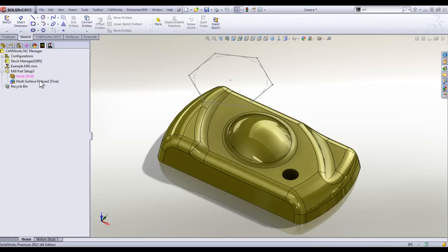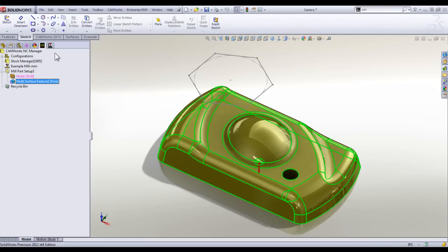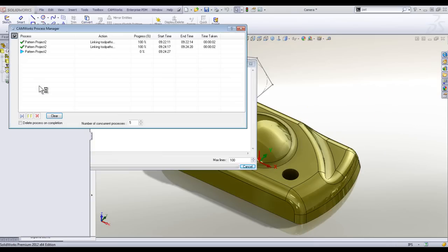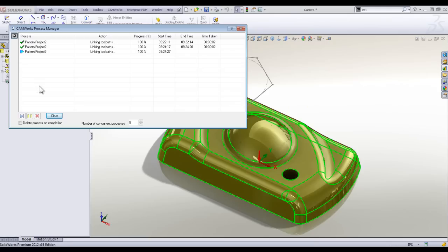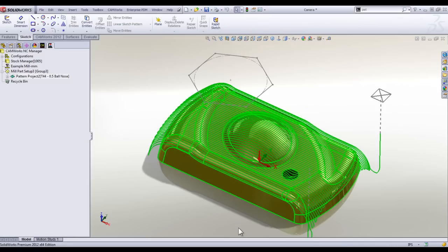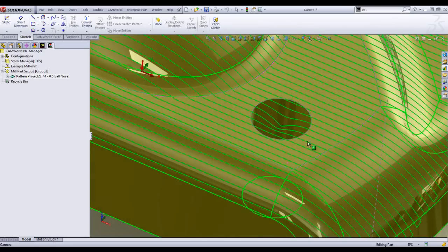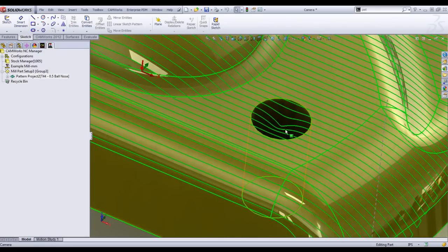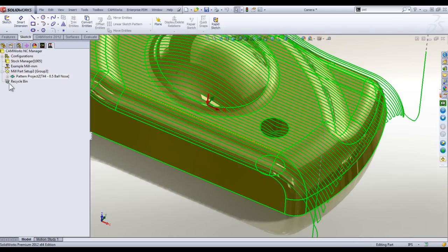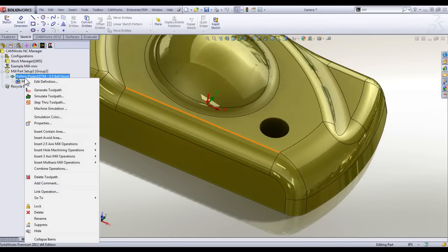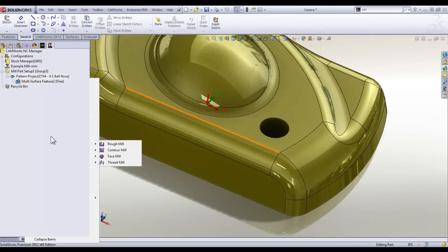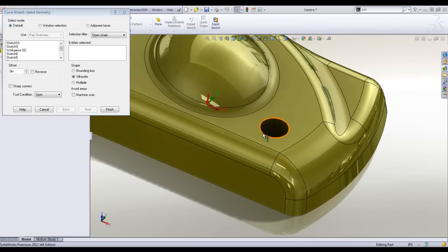All right. Now we got the drilled hole too. If we go in now and look at that, we can see how the tool path kind of jerks down there like that. So here would also be a good option to use a void area maybe. If I go in and select this edge here, be aware of one of the options we have. If I just check finish here, now it's going to avoid this hole.